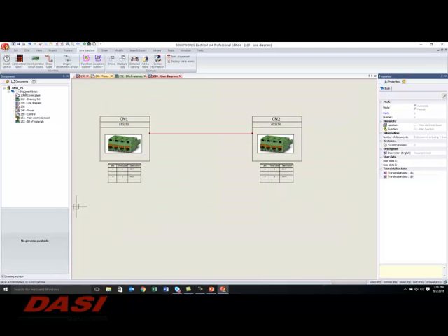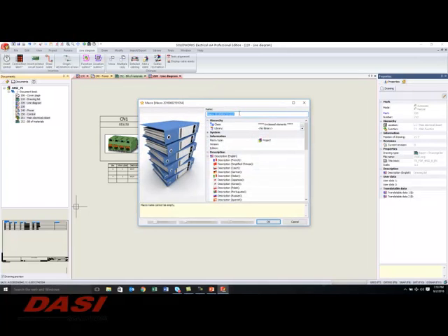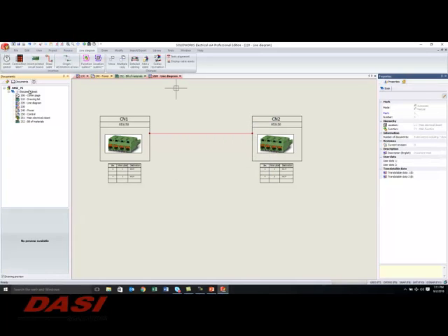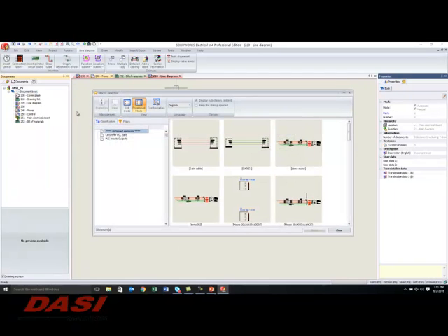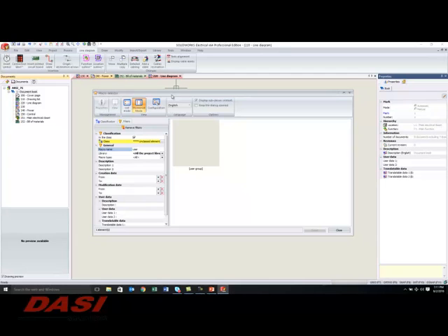I'm going to highlight some of these pages. So we'll highlight from here to here. Click, create project macro. We're going to call it user group. Just call it user group. No way I can find it. All right. Create that. Now I'm going to come back in here real quick. Right click, insert project macro, and I'm going to filter this to find my description of, I think it was project name, macro name. There's the macro name. User group. There it is right there.